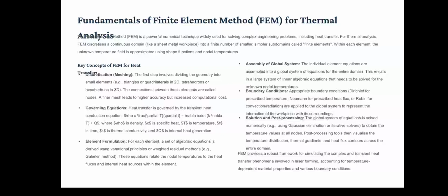Fundamentals of the finite element method for thermal analysis. Key concepts of FEM for heat transfer: discretization, meshing, governing equations and element formulation, assembly of global system, boundary conditions, solution and post processing. FEM provides a robust framework for simulating the complex and transient heat transfer phenomena involved in laser forming, accounting for temperature dependent material properties and various boundary conditions.